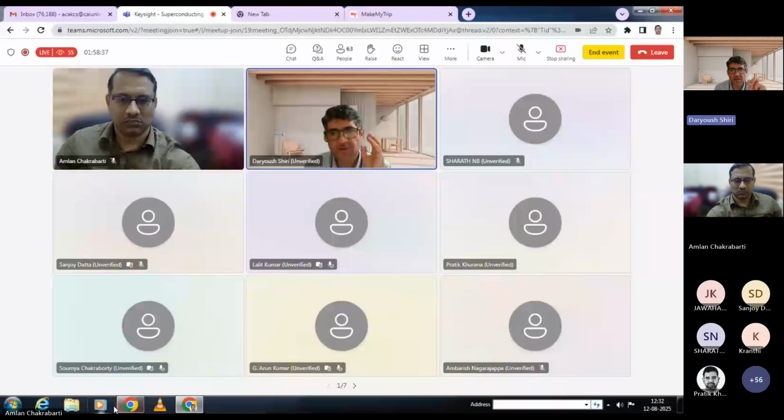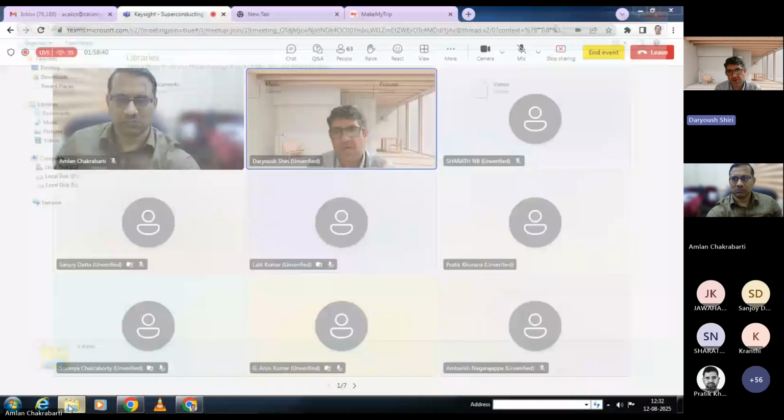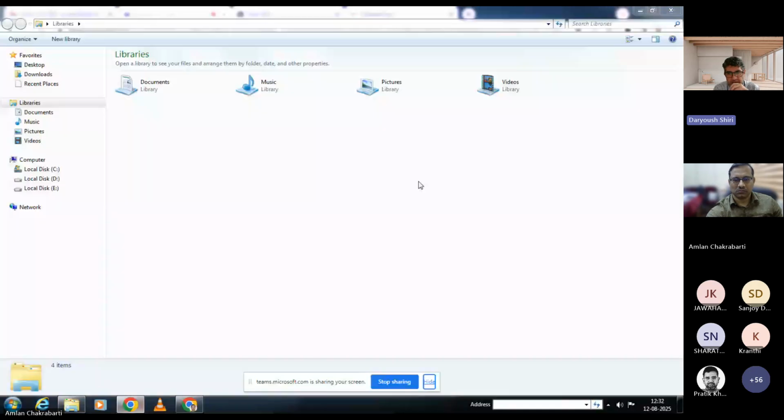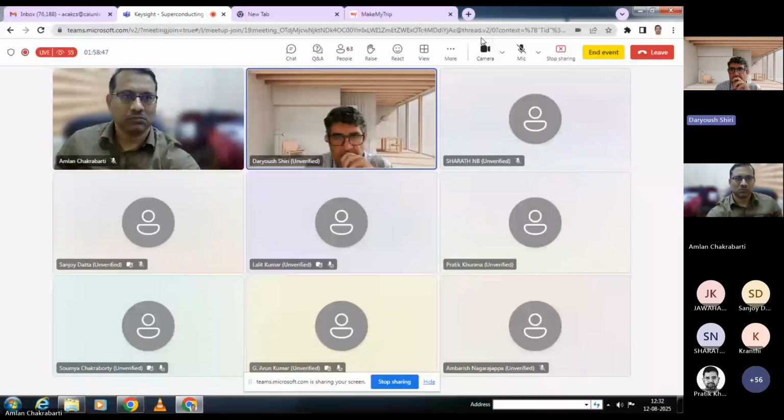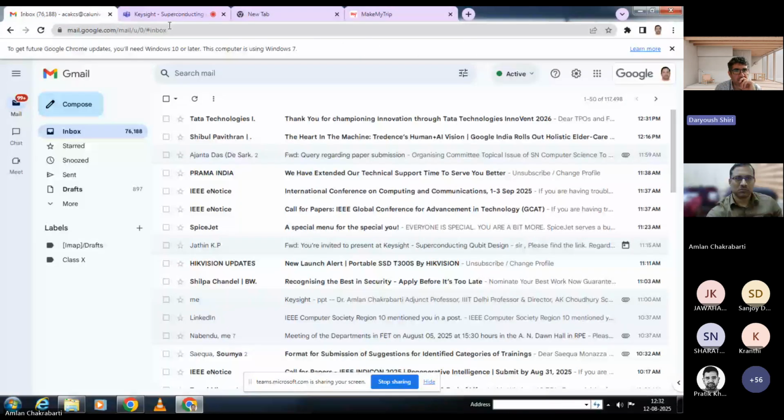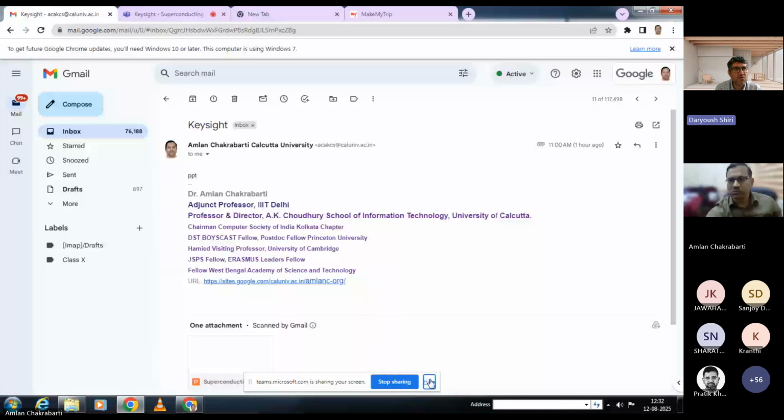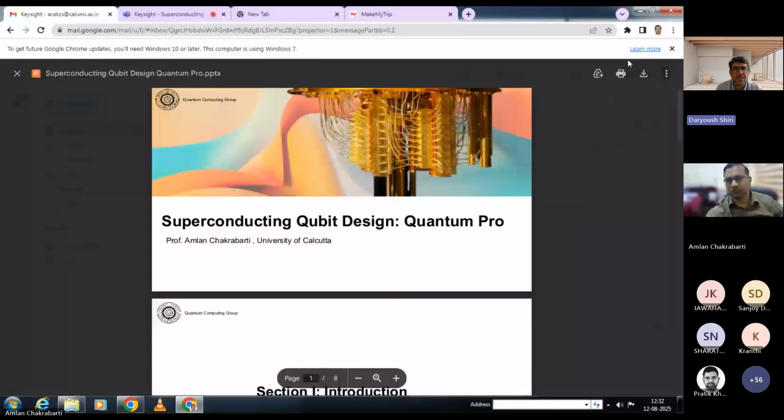But if you don't like it, or it's not flexible to put it where you want, after you created your layout, you can go there and manually add the bridge layer. So let me see if I can show you the layout. So these air bridges, the blue ones, are added by the tool itself. But if you want to add something yourself, let's say for some reason you need something here, just come here.